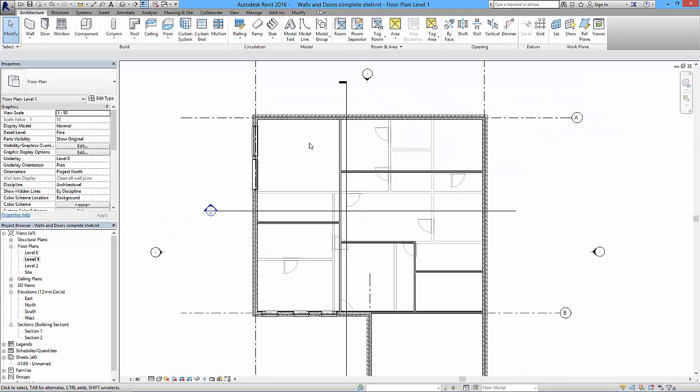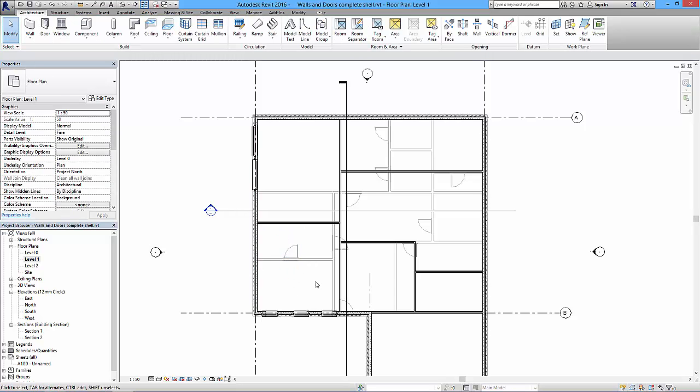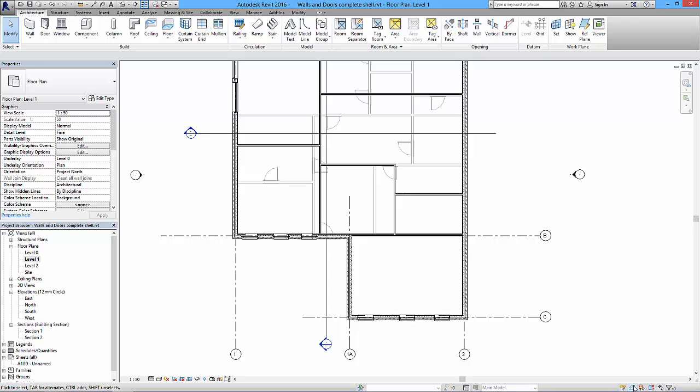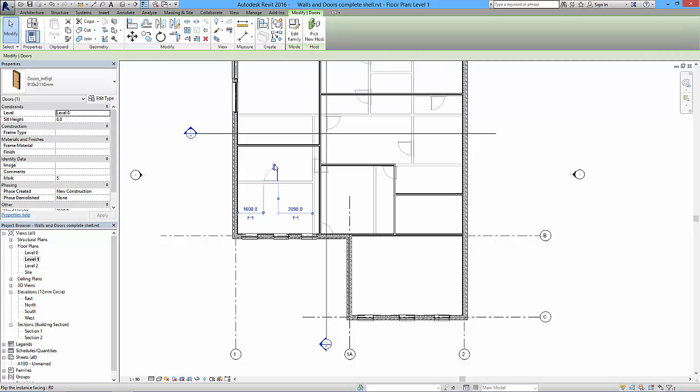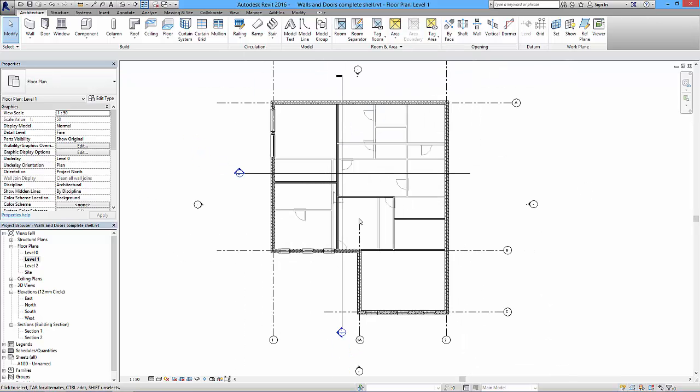So the most important aspects are to choose the type of window, to appreciate what's going on with the window and how you can adjust certain settings, and the witness lines and the flipping of doors in plan view. And the reason I can do that with this underlay object is simply because I've got this thing here, select underlay objects selected. If I was to click it so the little cross appeared, then I couldn't select them, I couldn't do anything with them. So this thing can be quite useful to adjust certain aspects of these doors. Okay, so we'll leave that at that.